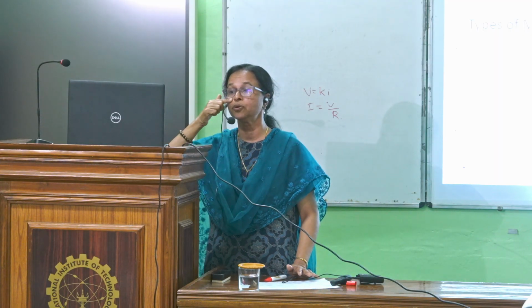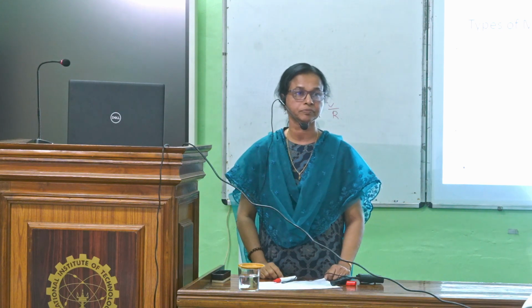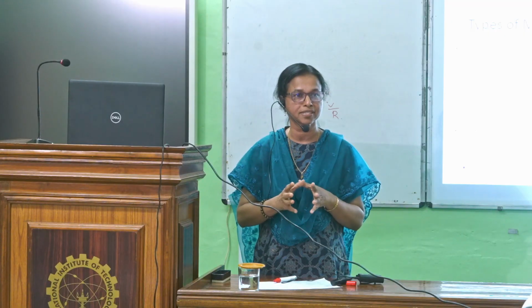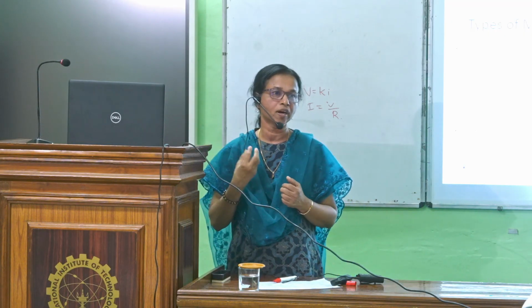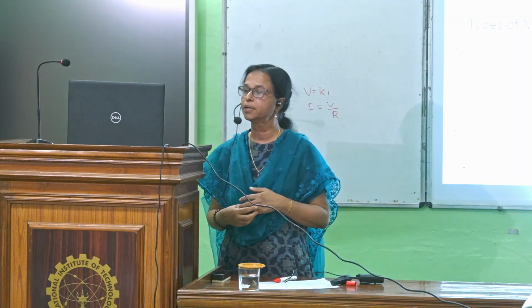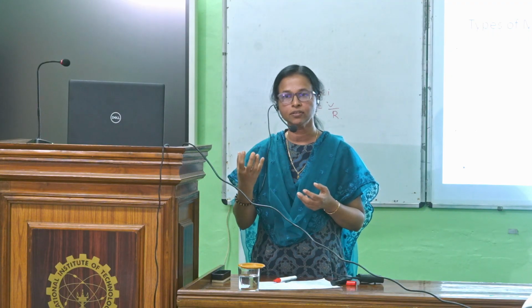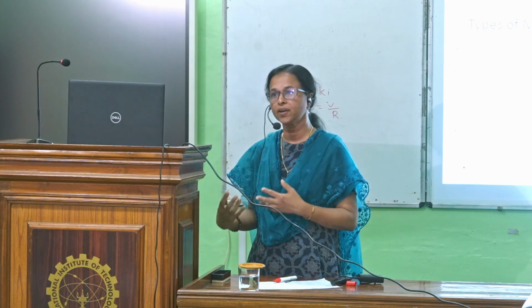Then based on spatial representation: lumped, semi-distributed, and distributed. So what is a lumped model? The entire area you are representing with one single characteristic. So you will get only one output at the outlet in this case. The semi-distributed model uses sub-watersheds. In each sub-watershed you can get the discharge, then you have to route and get the final output.